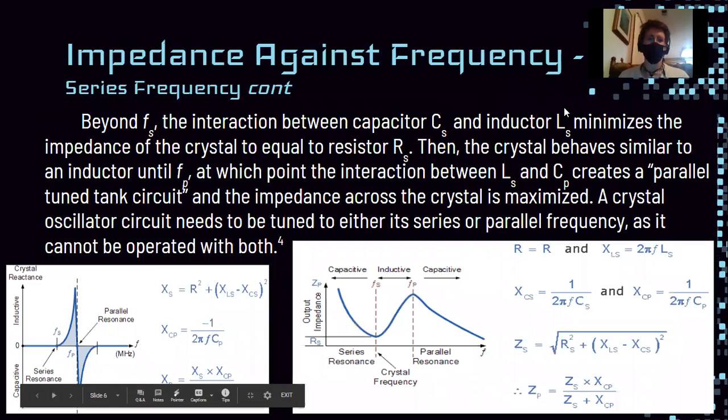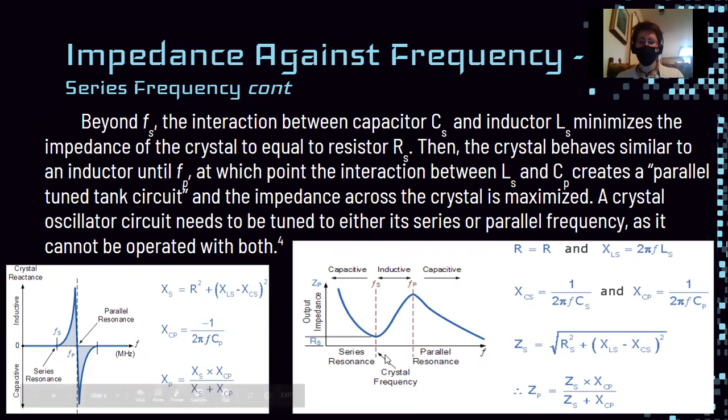The impedance against frequency also creates a way for the crystal to exhibit three different modes of resonance: the capacitive, the inductive, and then capacitive again.